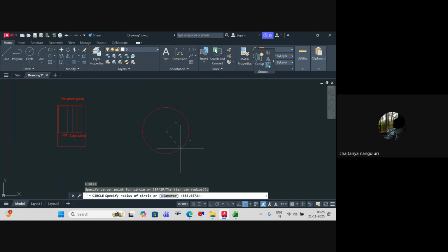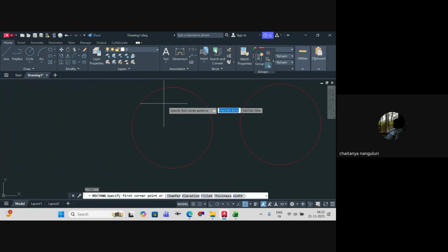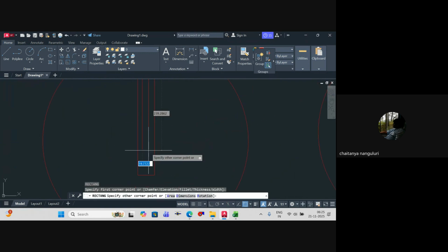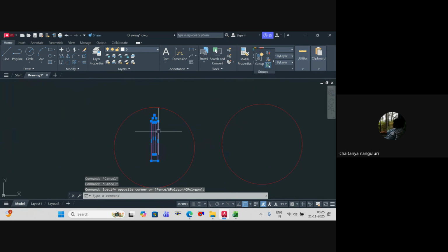Of course, even now you have the older models. Behind the device, you basically have two numbers. Each has 0 to 9 written, along with a small indicator with a notch in it. This notch is used for the screwdriver to rotate it. Understood? Here you'll have 0 to 9, and here also 0 to 9. So you can set 00, 01, 02. This is the units place, and this is the tens place.